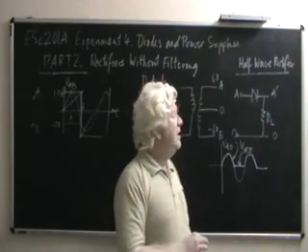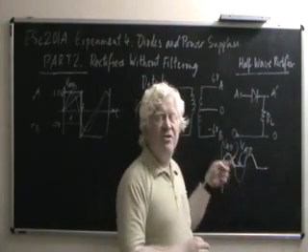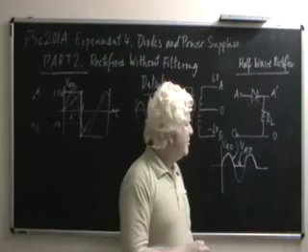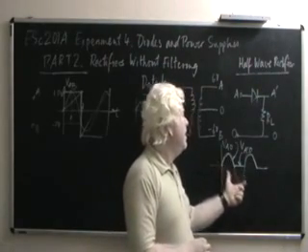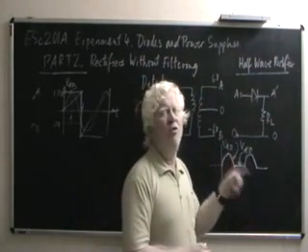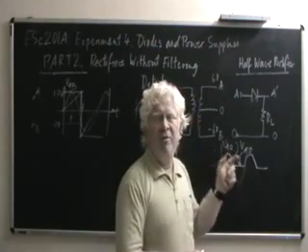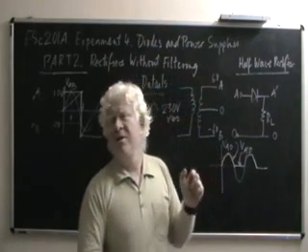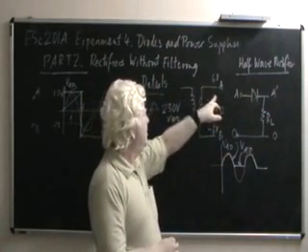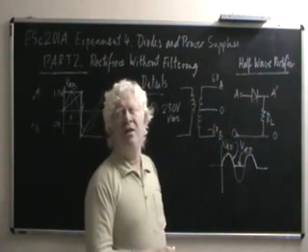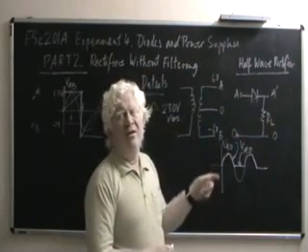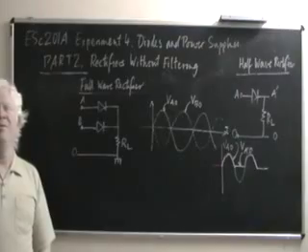However, the thing is still inefficient for a more complex reason that will become clear at a later point in this discussion. Right now, let us say that in terms of power this is not inefficient, but a better circuit can be built. What we will now do is to build the better circuit called a full wave rectifier. A full wave rectifier not only utilizes the waveform of the input side in the positive half cycle, but also uses it in the negative half cycle. How do we do that? Something very clever. Let's see what happens.